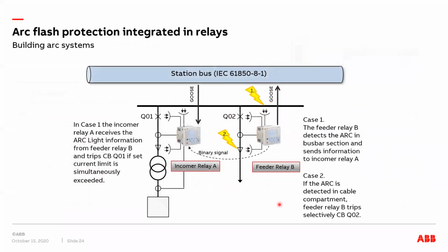The communication, as I said, is usually done with IEC 61850 and GOOSE communication between the devices. You can also do it with binary signals, but then you have to remember that that's a bit slower due to the mechanical delays in input and output contacts. GOOSE communication is optimal for this because the connection between the relays is also supervised.